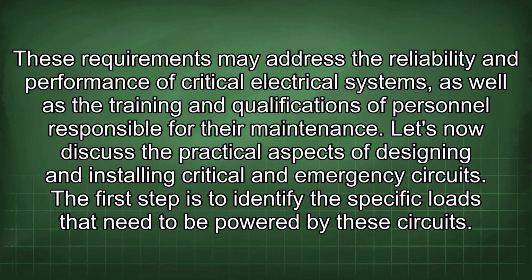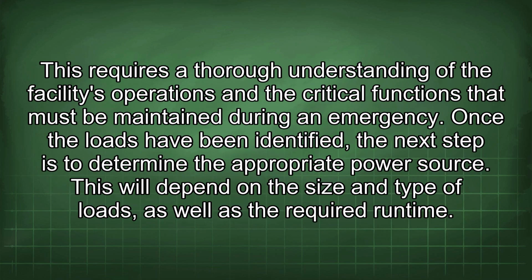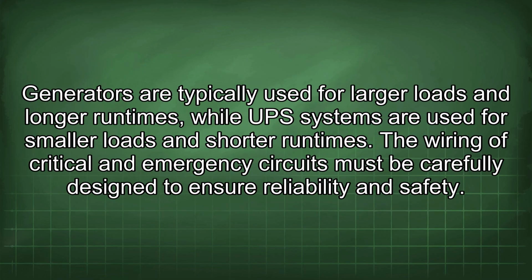Let's now discuss the practical aspects of designing and installing critical and emergency circuits. The first step is to identify the specific loads that need to be powered by these circuits. This requires a thorough understanding of the facility's operations and the critical functions that must be maintained during an emergency. Once the loads have been identified, the next step is to determine the appropriate power source. This will depend on the size and type of loads, as well as the required runtime.